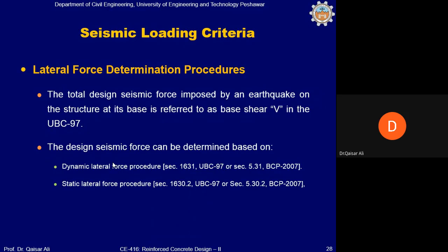by the earthquake, when the earthquake waves hit the foundation of the structure, the foundation along with the ground will move, but the superstructure cannot move by the same amount of displacement, thereby causing relative displacement and stresses. The structure must be designed to withstand those stresses, and at the same time, some damage will be allowed. So this analysis can be done using the UBC 97 procedure.